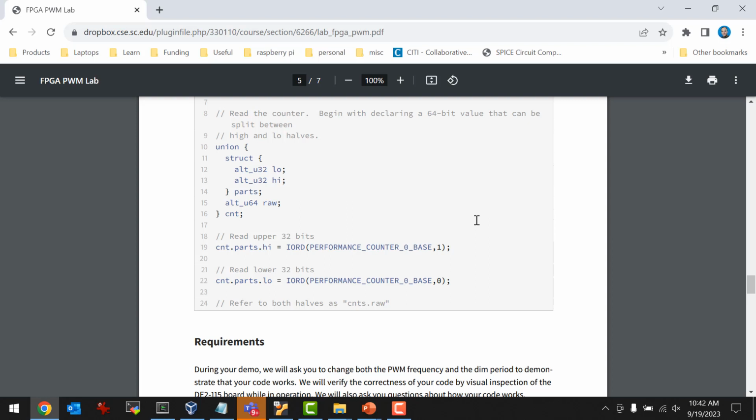This is in terms of words, because it's dumb. I don't know why they do it that way, but for whatever reason they use a word offset instead of a byte offset, as if we're not smart enough to figure out bytes and words aren't the same thing. So it's 0 and 1 instead of 0 and 4.